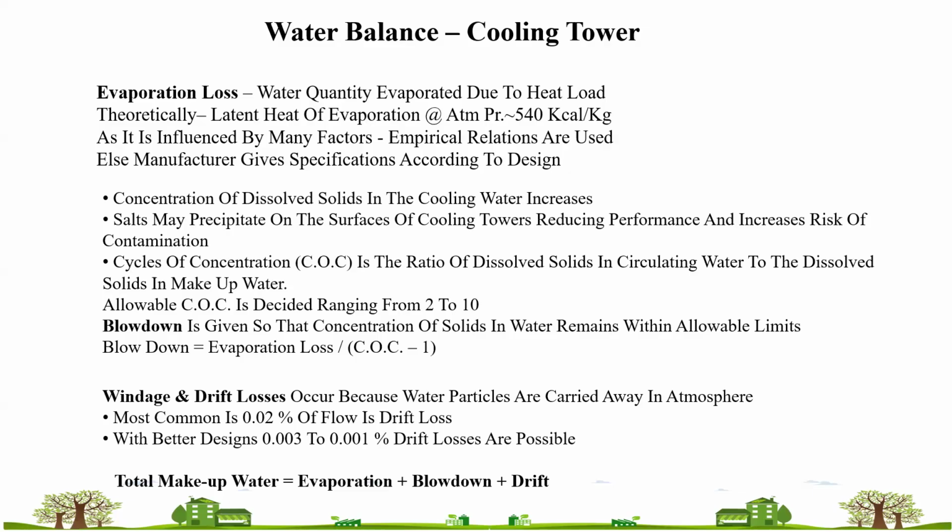So there is a chance of reducing the cooling tower performance. So the installation of ultra filters or sand filters in that particular path is mandatory, to improve the performance of your system. So it has to be installed. This is one of the major breakthroughs in the commercial building. If you are not using ultra filters and sand filters after the STP treatment, whatever STP output is given to the cooling tower as makeup, the cooling tower performance gets lowest due to this kind of phenomenon.